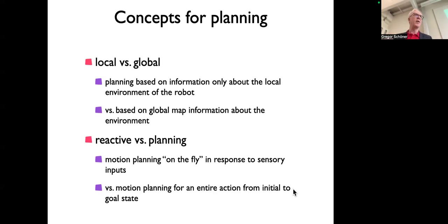I had that slide in the introduction talking about hybrid architectures, and that is the state of the art. Most current robotic devices, even arms, have what they call deliberate planning. It uses AI and symbolic representations to do sequences of steps in some plan that will be global planning. And then they have a reactive planner for the details, for the exact steering, and that would be local and use real-time sensor information.